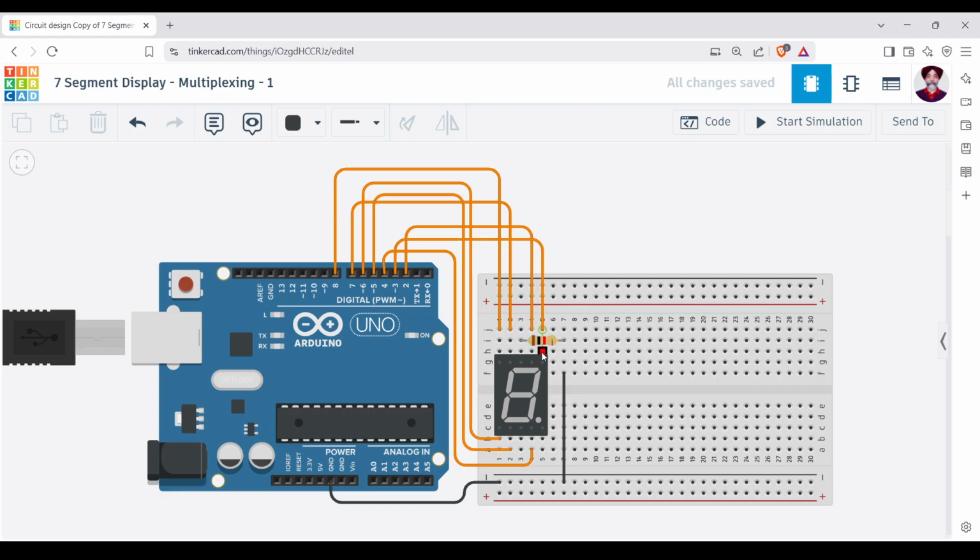For example, if I send a signal to A segment, A segment is high. The electric circuit has to be completed. Completed means from the anode side it is getting a high, and on the cathode side it should get a low, because the circuit has to complete, because it has to go to earth. It has to go to negative. If it is complete, it is okay. If it is not complete, then that display will not happen.